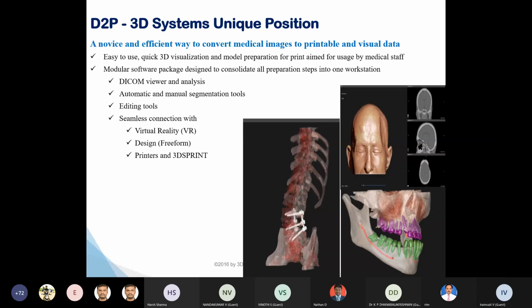For example, initially if I want to convert the data, we have to fix the threshold value. Sometimes, if a case has screws and plates, when we are taking a CT there will be some scatterings. That scatterings we have to manually remove. We have to work on the whole 300, 400 slices layer by layer, edit it, remove it. We, as engineers or biomedical engineers, are not well versed in anatomy. Of course, we have to learn it. If we miss it, the whole thing fails.